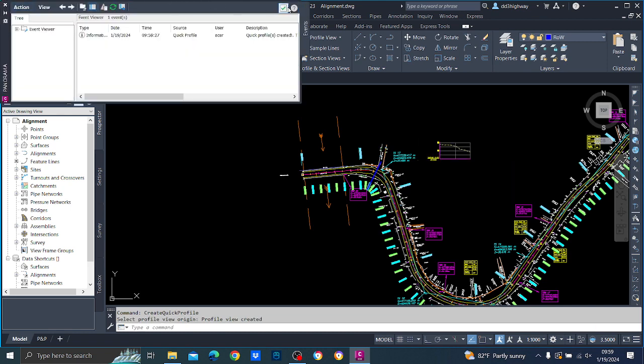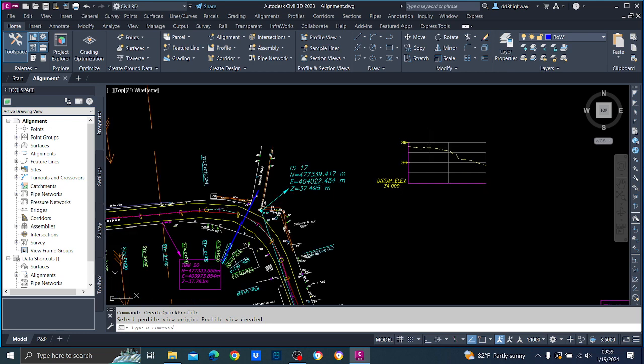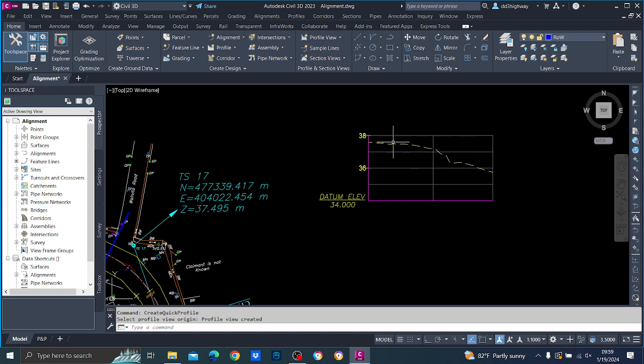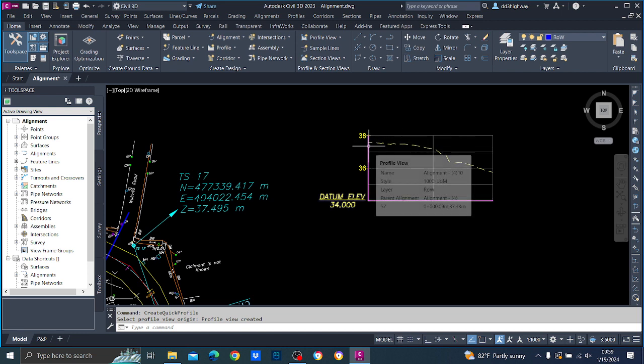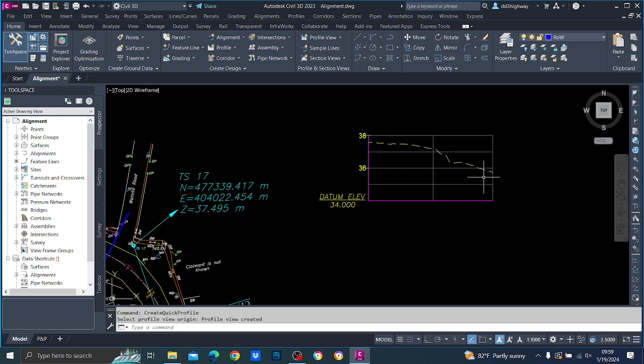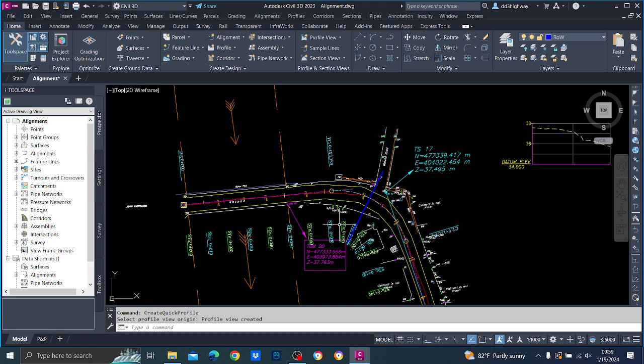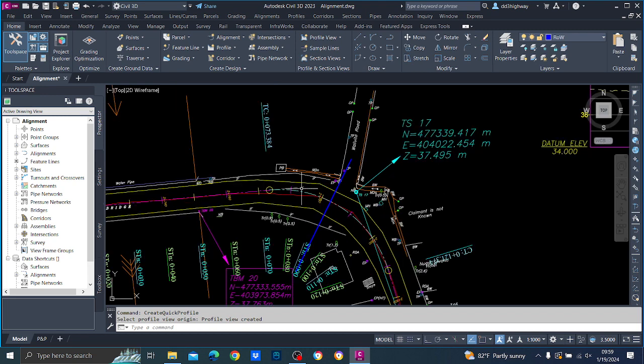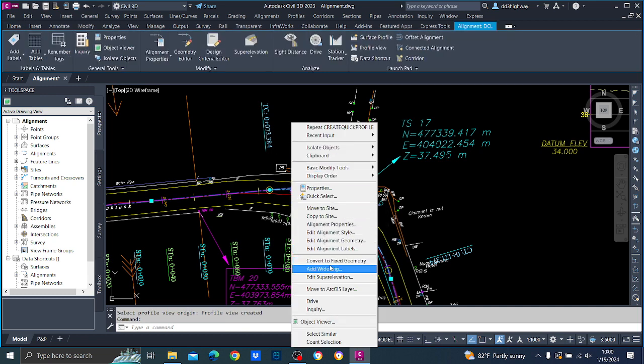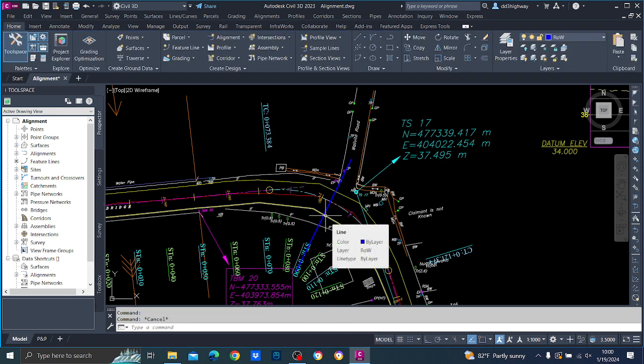Now this is the cross section of this section. Here can you see, somewhere around say 37.5 is coming to 35.5, so that means it's somewhere around a 2 meter gap, right? So you have to decide whether you are allowing this 2 meter or not. Now if I am going to change this, I select this, say, now our toolbar is gone, right?